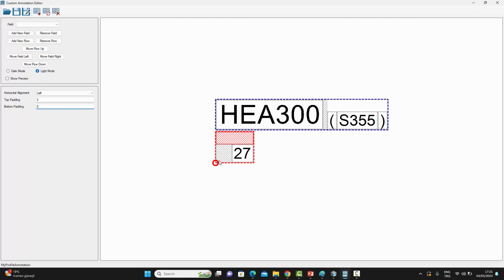And if I wanted to, this is the anchor point. This little round circle you're seeing over here is the anchor point. So sometimes these fields are used with text leaders in annotations, and you want the text leader to go in between these two lines. You want a line in the middle, something written on top, then the text leader line, and then something in the bottom. So in that case, you can create this little gap over there.